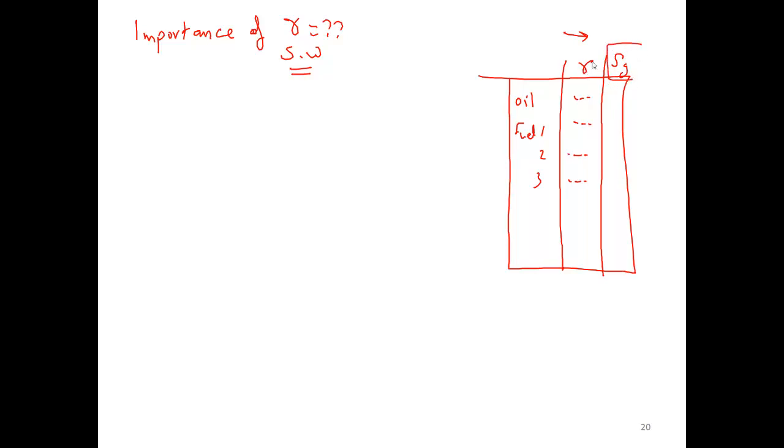Now this you have to specify the temperature, because remember, gamma is rho times G. Now G, we're on Earth and we're assuming it's constant, almost 9.81. We're not gonna really discuss the variation in G, but if you have a difference in temperature, then the density is going to change.